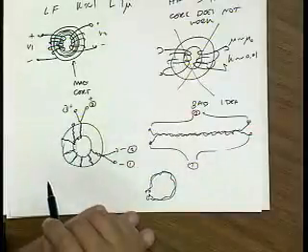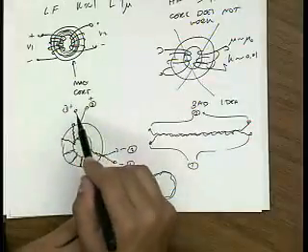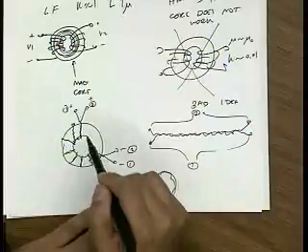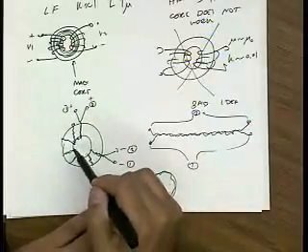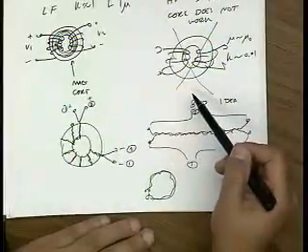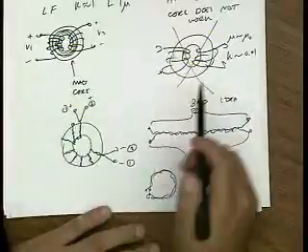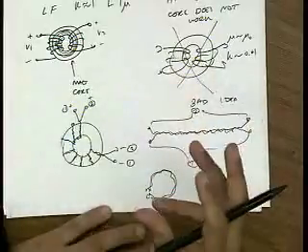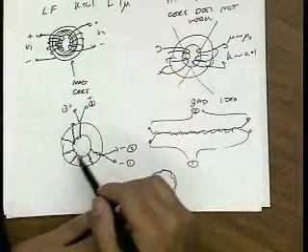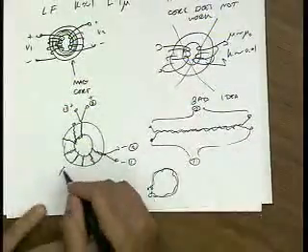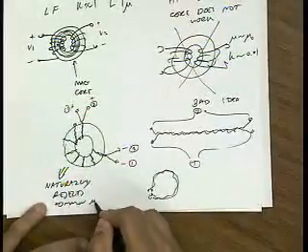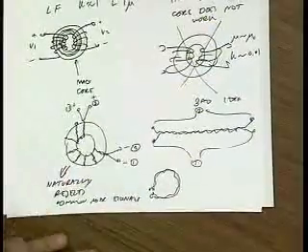Common mode signals, on the other hand, actually for a common mode signal, I put the same current through these two wires. So it just looks like one wire wound around here like this. And that would generate a lot of magnetic field. So a common mode signal would generate flux in the core. And it turns out that these things don't work because they actually produce loss at high frequency. So because of the lagging, because the magnetic moments, the magnetic domains lag the signal, they actually look like a loss term. So they make our mu imaginary. So for a differential signal, because there's very little magnetization, there's very little loss. But for a common mode signal, there's lots of magnetization and therefore lots of loss. So this structure naturally rejects common mode signals. And later on, we'll see why we want to reject common mode signals.